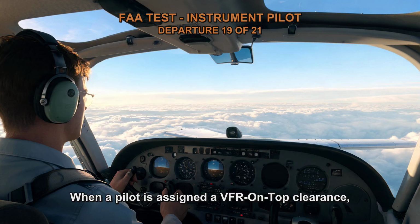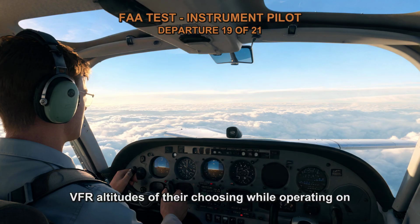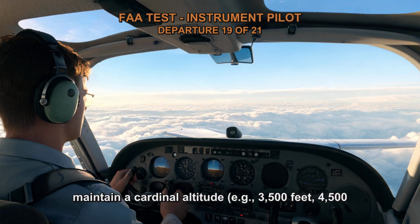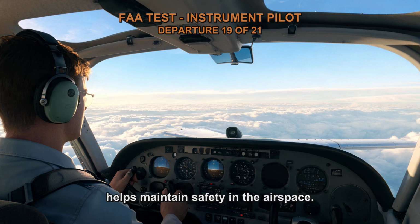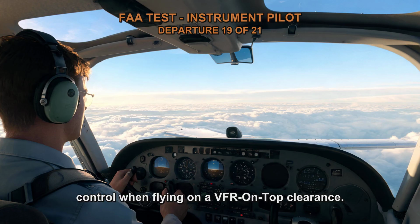When a pilot is assigned a VFR on top clearance, it means they are authorized to fly at VFR altitudes of their choosing while operating on an IFR flight plan. In this case, the pilot is required to maintain a cardinal altitude, e.g., 3,500 feet, 4,500 feet, etc., plus 500 feet. This ensures vertical separation from other aircraft and helps maintain safety in the airspace. It is important to comply with the assigned altitude and any instructions given by air traffic control when flying on a VFR on top clearance.